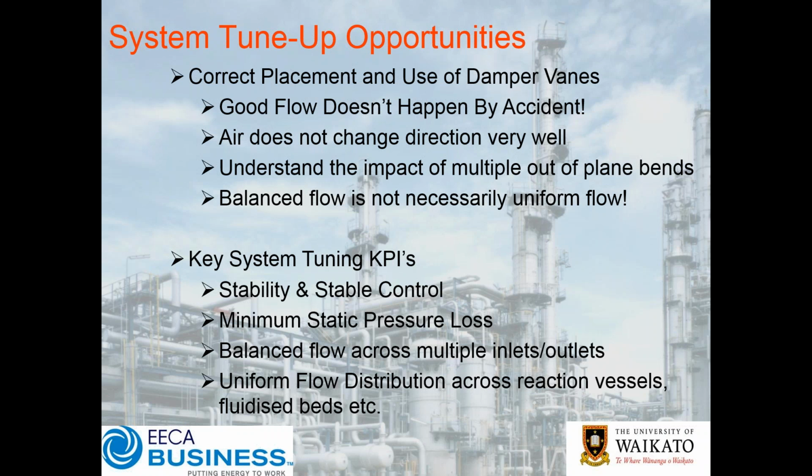Obviously part of that, then we want to minimise our static pressure loss through our system. As we do all of that, we should get balanced flow across any situations where we have multiple inlets or outlets. And then as we do that, we can then look to have uniform flow distribution across our reaction vessels, fluid beds, etc. And if we do that, we'll then get benefits in terms of better uniformity in our product that we're making, tighter controls on the specification or functional properties of whatever product we might be making, better quality metrics and so forth.